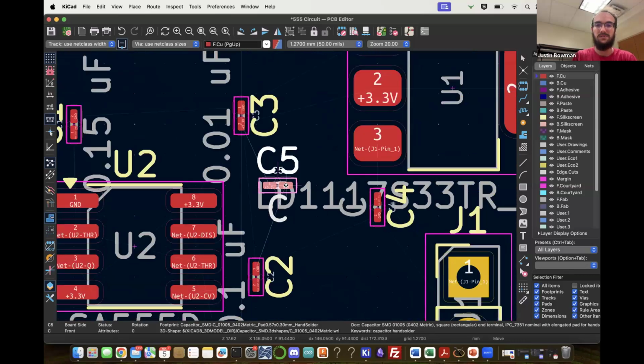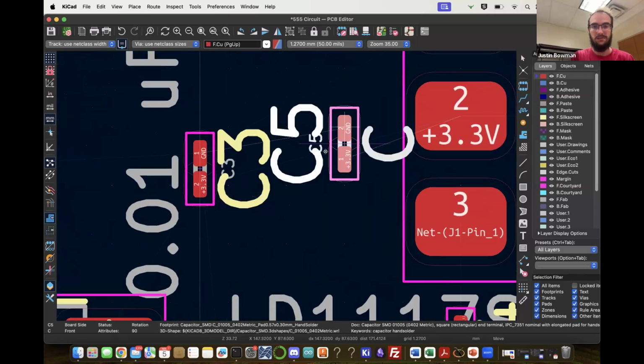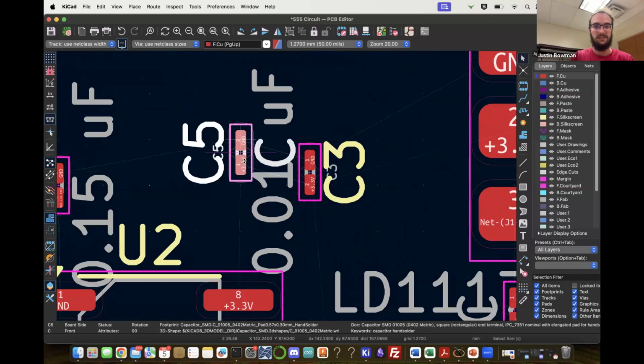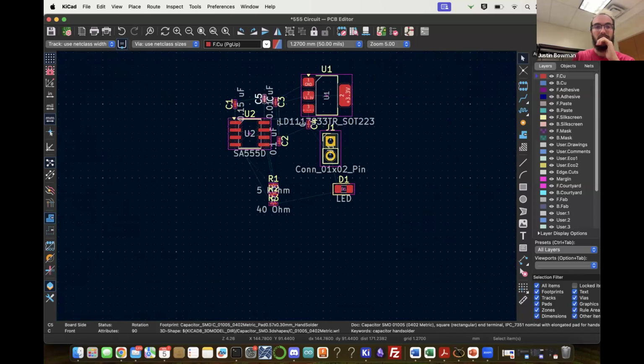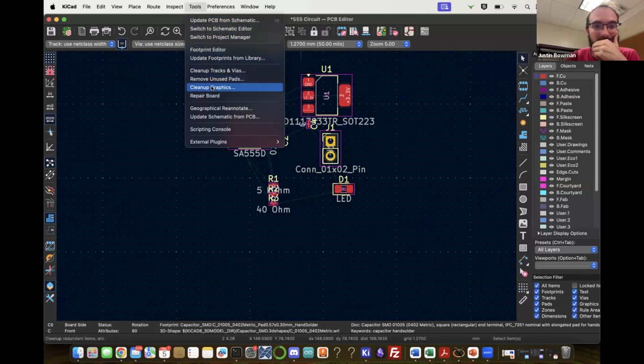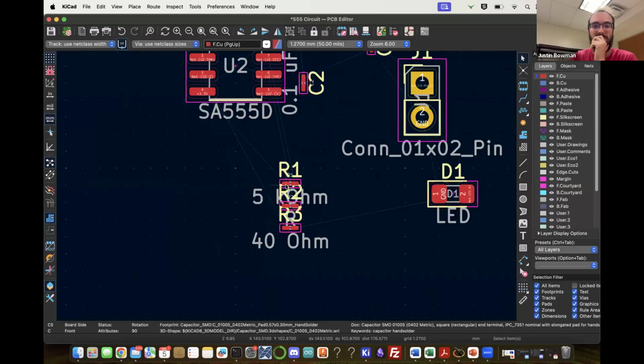This is again 3.3 volts and ground, so that can also go close to this. There's no automatic PCB layout, no special red button. I haven't found it, it might be there. Question: I'm new to KiCad, I'm just learning, and even for Eco, you can't place the components automatically, you have to make the layout, and it has auto routing and stuff, but not in place.